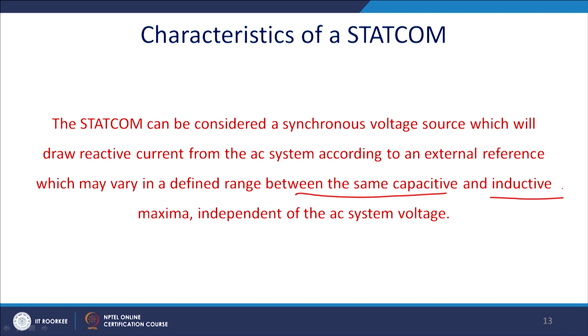So, it is a very effective tool when a sag occurs. We shall see in our next class that the reactive power compensating capability of the SVC decreases in transient and other conditions, but the Statcom can compensate the reactive power very well even in a disturbed system.